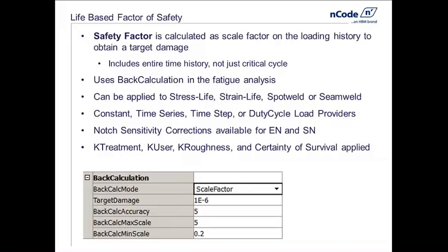It's also available in spot weld and seam weld. It can use any of the time-based load providers: constant, time series, time step. It allows for notch sensitivity corrections to be done both for stress life and strain life, and also allows things such as surface finish corrections as well as certainty of survival to be applied to it prior to the calculation.